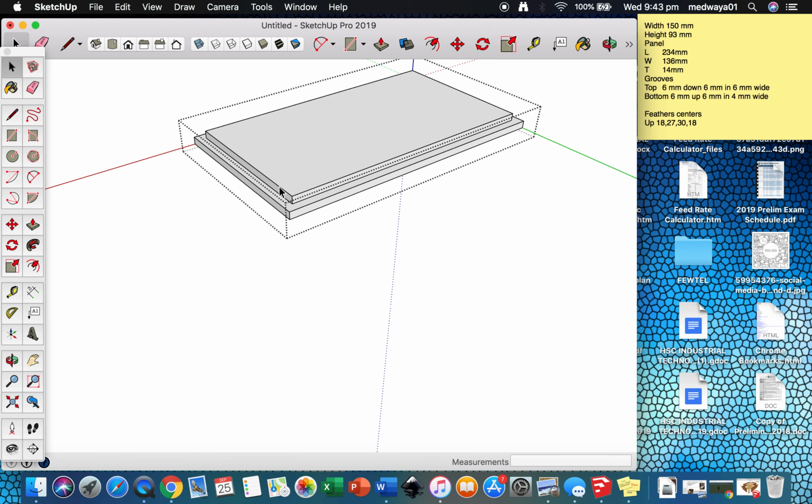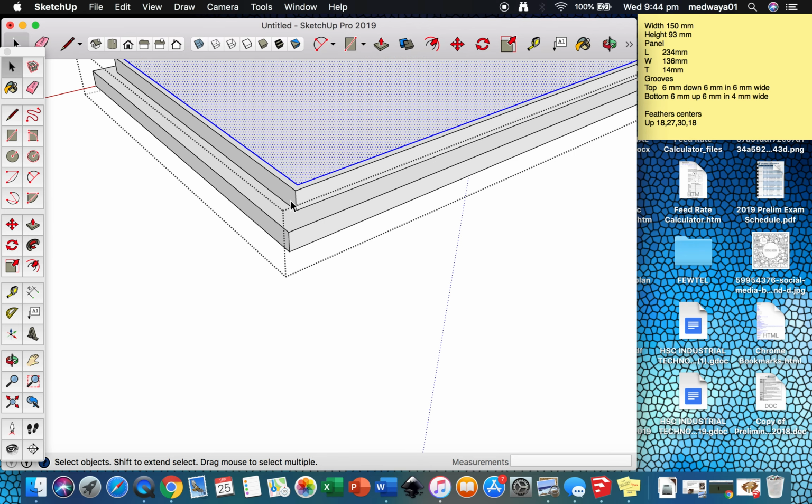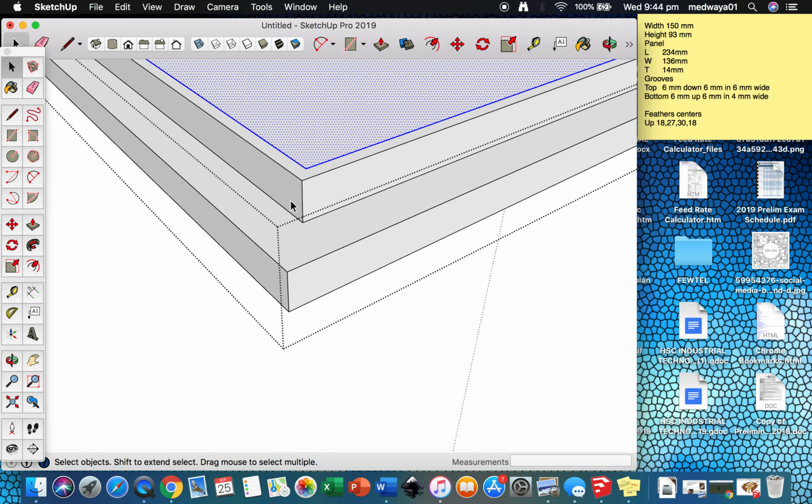To do that, first of all, we're going to use the offset tool again, which is F for offset. We're going to select that surface there. We're going to come in 2 millimeters. So type 2, enter. We're going to do the same again, double click. And we're going to zoom in here because it makes it easy to do this while we're looking close. We're going to hit the M for move copy tool. We're going to select that edge there as a vertical surface to move along.